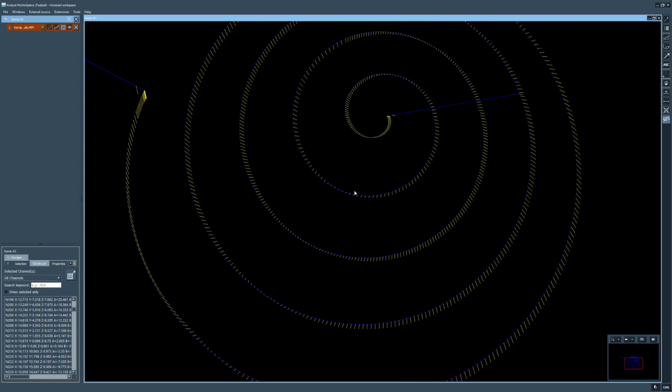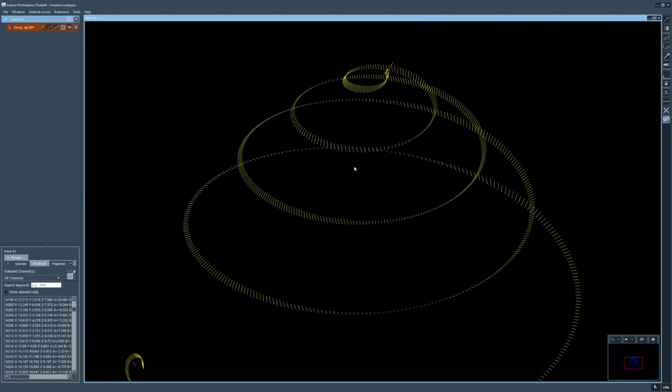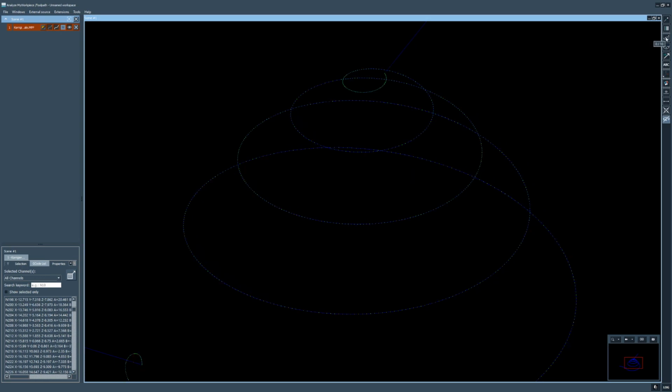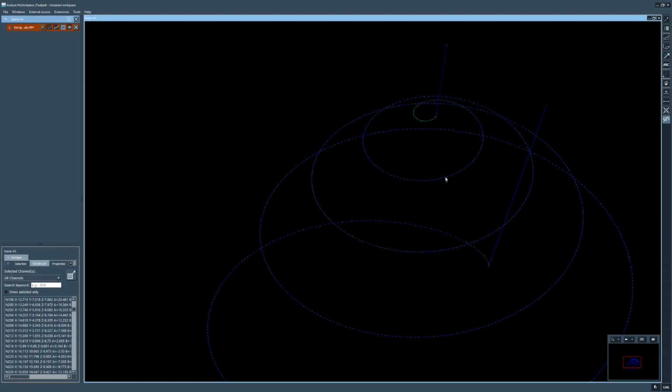Then it is always worth checking the tool orientation, because if it changes quickly within a few interpolation points, this could be a reason why there are speed drops in your actual process data. So always make sure to check it in case you have process issues in terms of abrupt speed decreases.